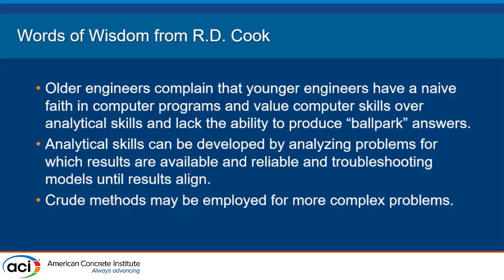You can use analytical skills that can really be developed by analyzing the problems in the results, by using hand calculations that they've used all the way back into the 1800s, 1900s, to just see, does it make sense? Even though you have a complex model, it still should be in that same ballpark answer. You need to have an understanding of the ballpark. And sometimes crude methods can really help you identify problems in your model and really short circuit your QA, QC of that model and finding that there is a mistake.